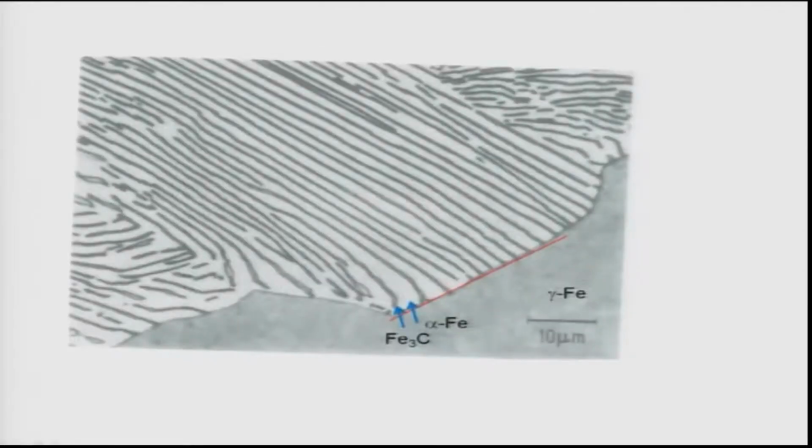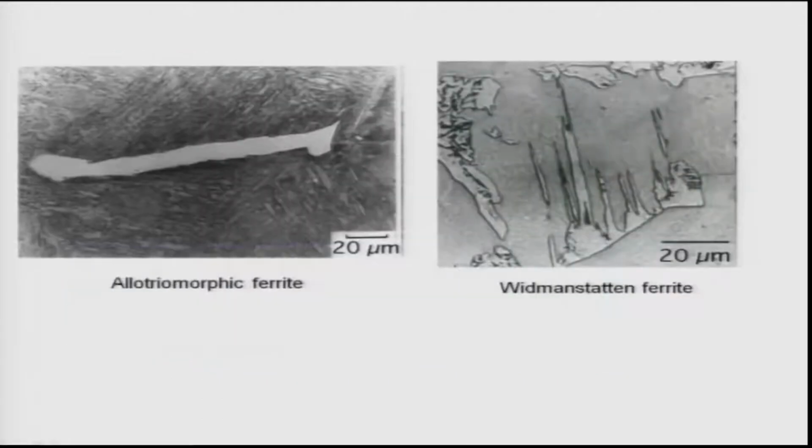This is the first thing I showed you, that if austenite is cooled below 727 degrees Celsius temperature, it will lead to formation of Fe3C, which is shown as a black or grey colored phase, and alpha, which is known as alpha Fe. Basically, it has almost no carbon, therefore, it is almost like pure iron, and the interface looks like a very curved one between the gamma and the product phase. And we discussed a lot about these, so let us not do that.